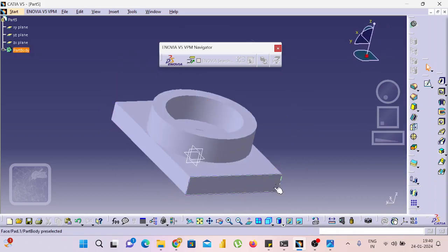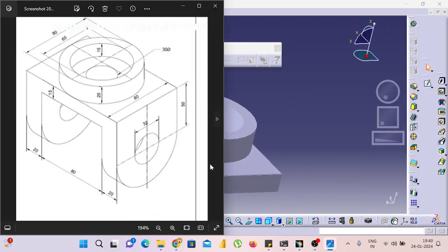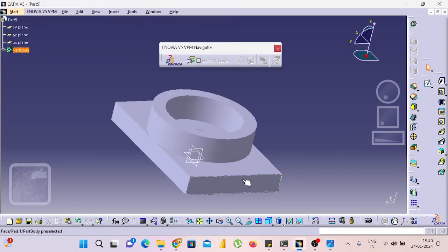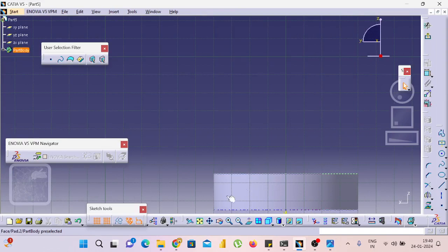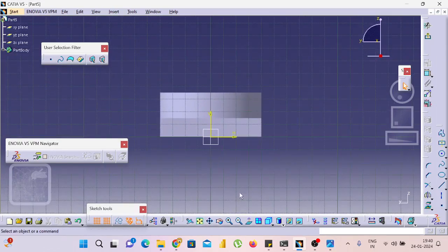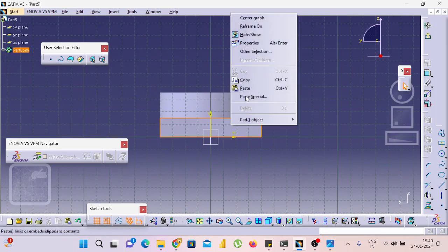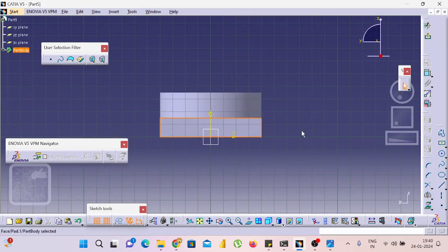Right. After that, I need to draw the flanges. For flanges, if we draw one flange, we can mirror it for the other side also. Right. For drawing the flange, we select that reference plane side and select this one. Please enter fit all in. Right, here also we can see that reference is on, so that it will be highlighted. Next, take this rectangle.